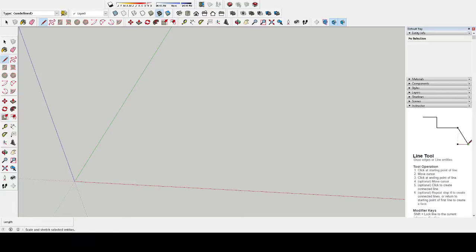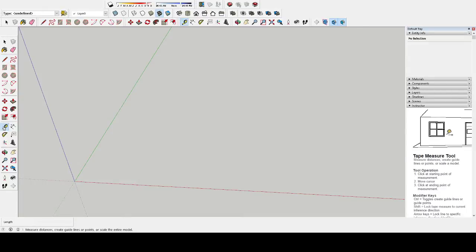First, I'm going to introduce the tape measure tool to give you the reference line. The reference line gives you an exact measure, not inexact. Try to follow this way. I use this as the basic axis. Drag here. Okay, 333. Still 333, don't worry. Put it at any location, any position is okay, but make sure your reference line follows the right axis.